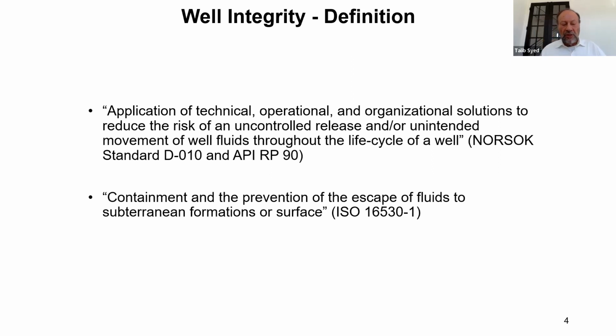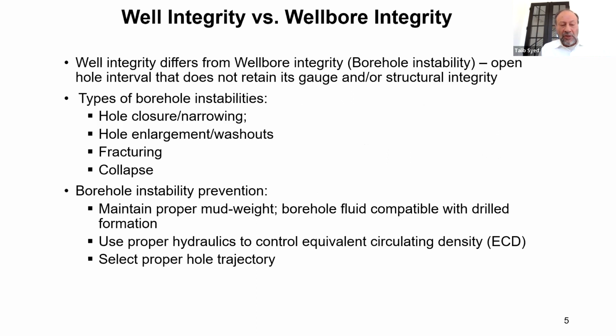The ISO definition and alternative definition is the containment and the prevention of the escape of fluids to subterranean formations or to the surface. So if you were to ask a layperson, what is the definition of well integrity, he or she may say, just keep your production or injection fluids within the pipe, and then you're fine.